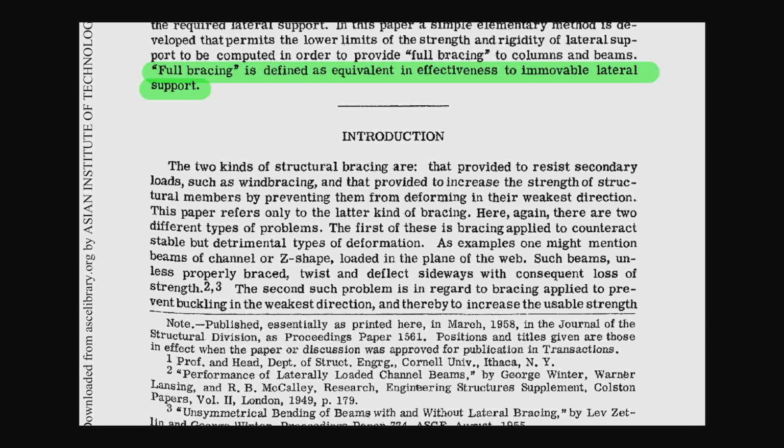The brace of our interest is the brace for the instability. We provide a brace such that the instability of the column or beam will be resolved by increasing the lateral restraints against lateral displacement and so on.